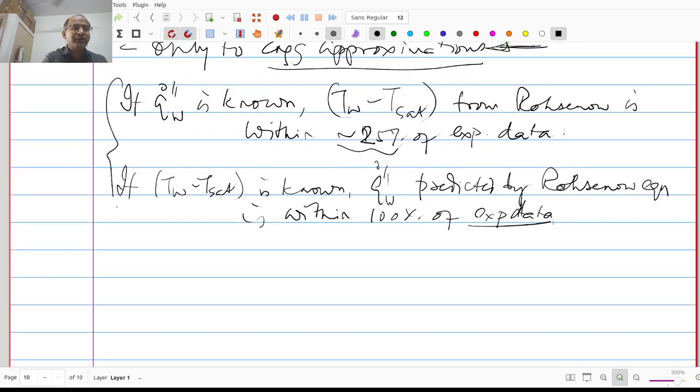But then you say that, all right, we'll then work with factors of safety if I have to design for this. Okay. So particularly, for example, if I am looking at power plant boilers, if film boiling starts happening on the tube surfaces, then the tube surface temperatures can go well above the melting point of steel, because the furnace temperatures are about 1700, 1800 Kelvin, or maybe higher than that, 1700 degrees Celsius, and therefore about almost 2000 Kelvin.